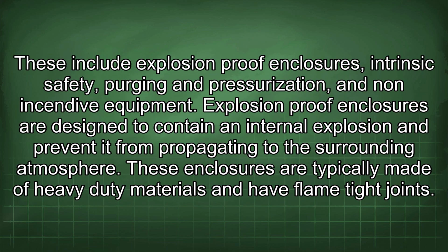These include explosion-proof enclosures, intrinsic safety, purging and pressurization, and non-incendive equipment. Explosion-proof enclosures are designed to contain an internal explosion and prevent it from propagating to the surrounding atmosphere. These enclosures are typically made of heavy-duty materials and have flame-tight joints.